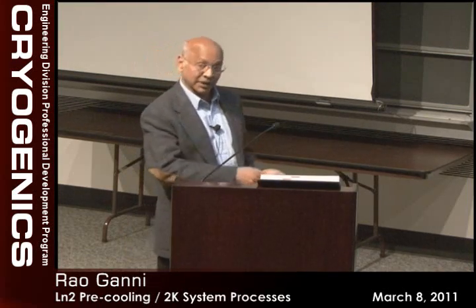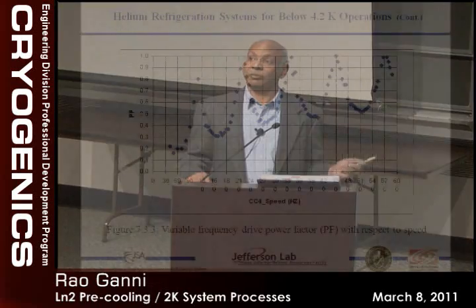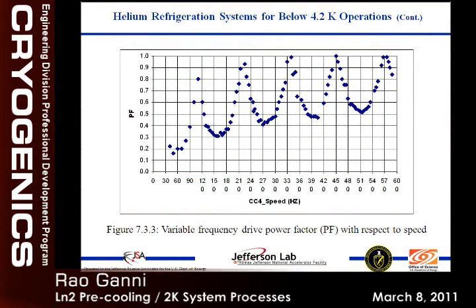And when we built the SNS, this was a new record. We never even thought we would fall into this trap where we built this just like JLab, put everything together, started, and it doesn't start. 3 days, and we're scratching our heads. And I said to Fabio, I can't see anything wrong on the cold compressor side because I know the wheel, I'm involved in turbine designs, I built some of them. It's not coming from the turbine.